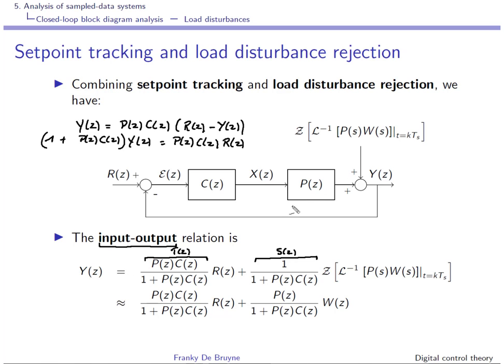and you can do the same exercise for the relation between this signal over here and the output Y(z). And as I've said, this yields the complementary sensitivity function T(z) and the sensitivity transfer function S(z).